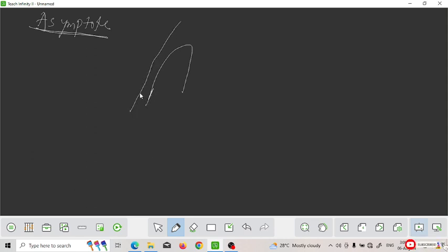See, this line and this line don't meet and they are parallel to each other. So this line is called the asymptote of this curve. Okay, so rectangular hyperbola is such a case in which the asymptotes are obtained as lines parallel to their respective curve. Okay, so rectangular hyperbola: when the section plane is parallel to the axis and the included angle between the asymptotes is 90 degrees, then the hyperbola is called a rectangular hyperbola.